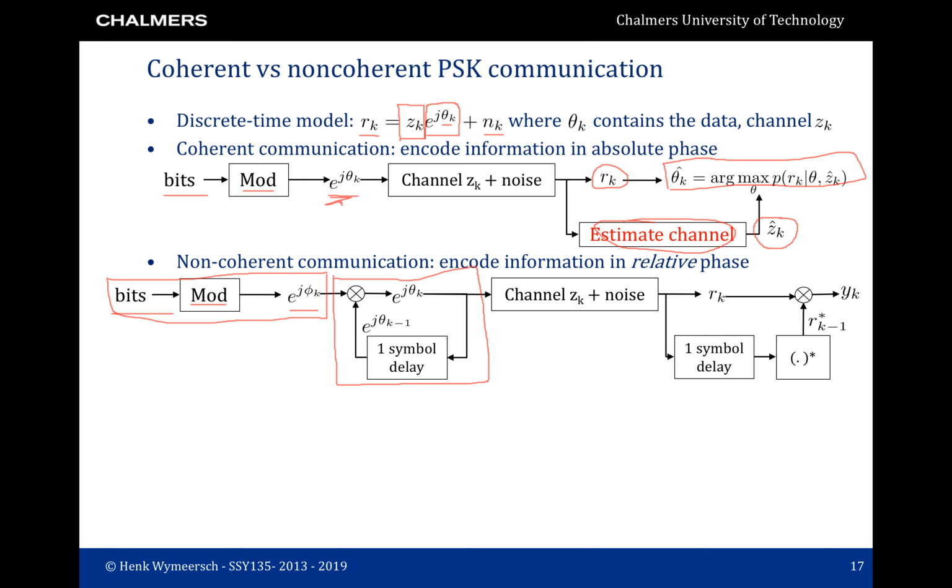What we do is take the previously transmitted symbol and multiply it with the current NPSK symbol, and that's what we then transmit. So this is again a point on the unit circle. It's a phase. It actually looks the same as an NPSK symbol, and we send this over the channel. So we have a simple code before we go into the channel. Then we apply the channel, we add noise, and then we have our observations Rk.